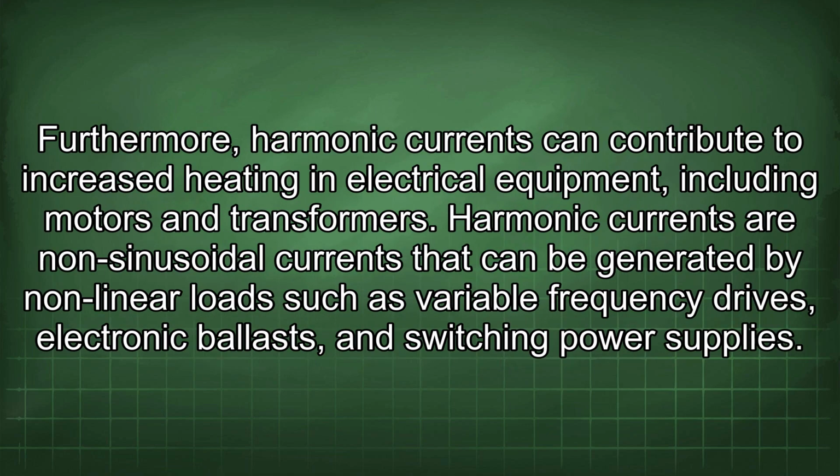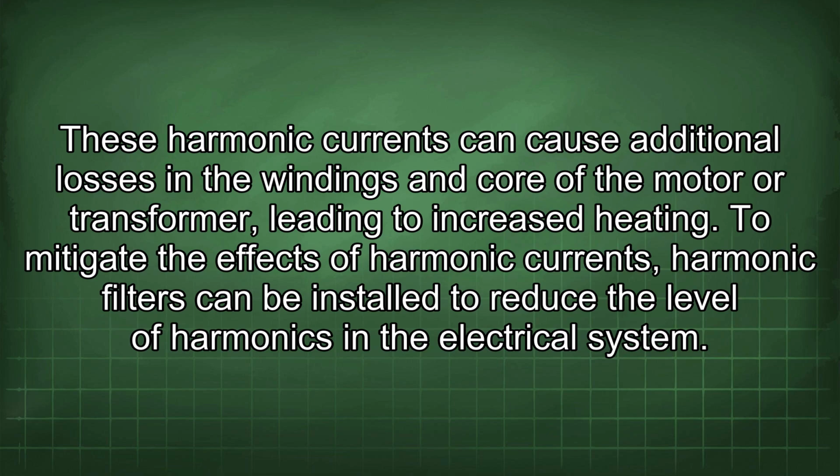Furthermore, harmonic currents can contribute to increased heating in electrical equipment, including motors and transformers. Harmonic currents are non-sinusoidal currents that can be generated by nonlinear loads such as variable frequency drives, electronic ballasts, and switching power supplies. These harmonic currents can cause additional losses in the windings and core of a motor or transformer, leading to increased heating. To mitigate the effects of harmonic currents, harmonic filters can be installed to reduce the level of harmonics in the electrical system.